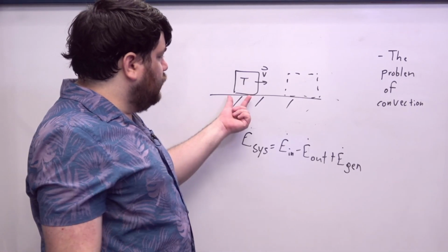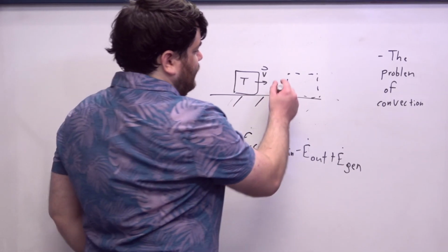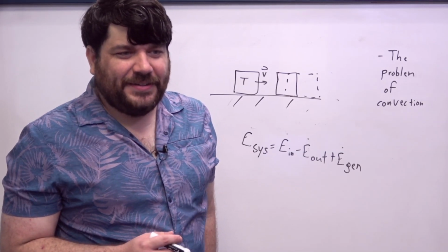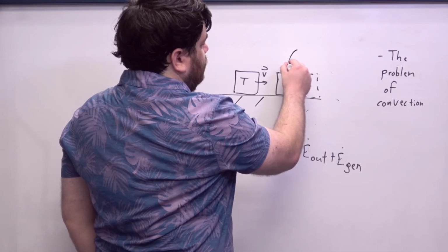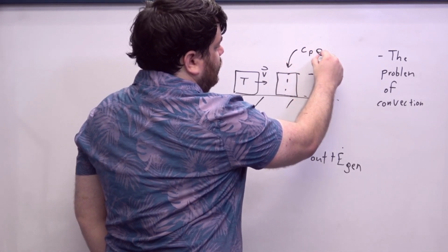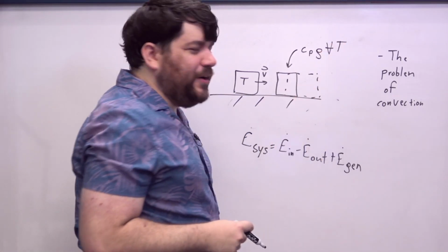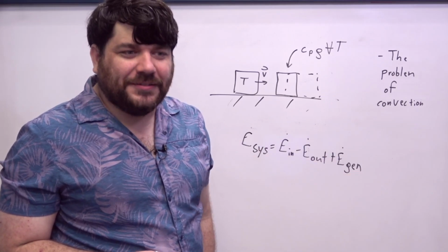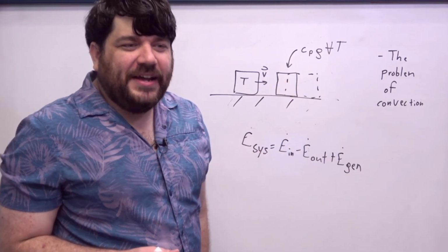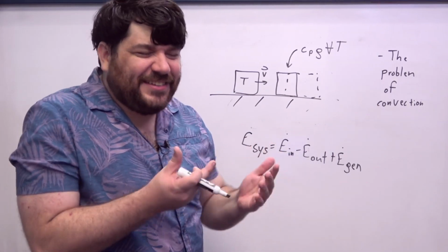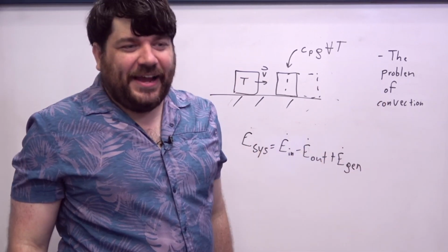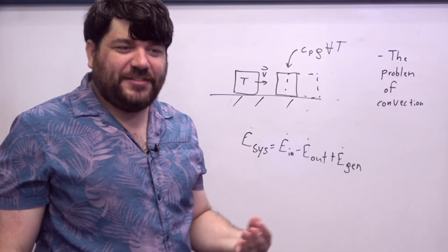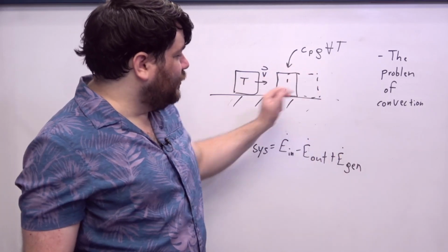But what happens as this block starts to slide forward and then eventually enters into this region, right? As it enters, this block has, as far as we know, a thermal energy which we have described as being this. And that thermal energy is now flowing into the boundaries of this region of space, not because of a heat flux, right? Not necessarily because of the fact that that energy is moving in as a result of a temperature difference or a thermal gradient. It's moving in there because there's a non-trivial velocity that is literally moving the matter with this thermal energy into the volume.